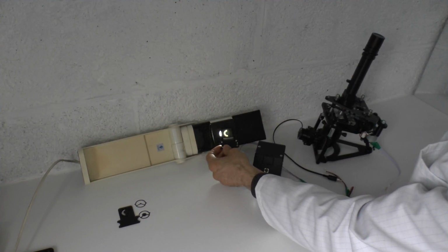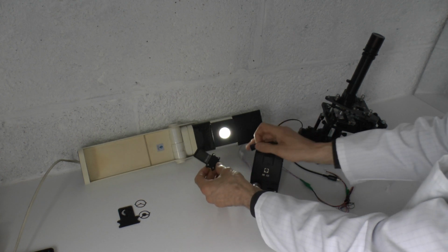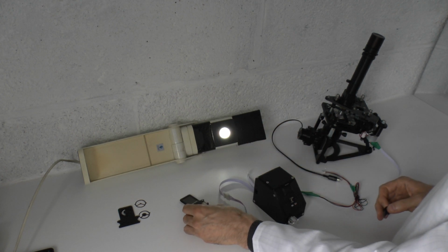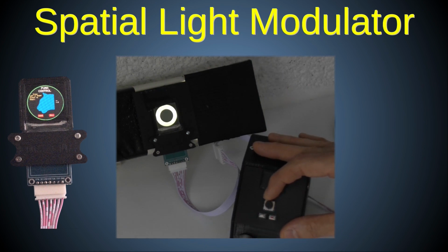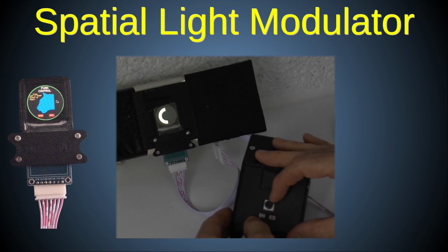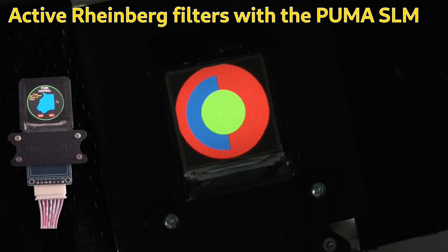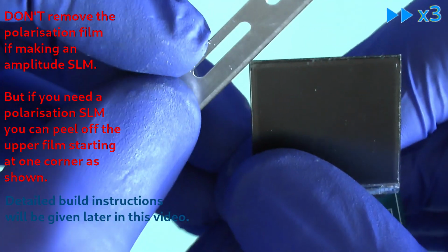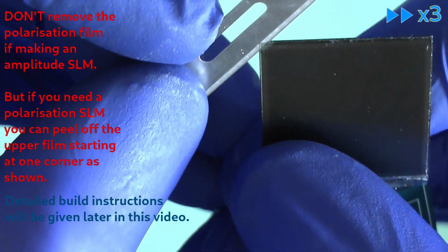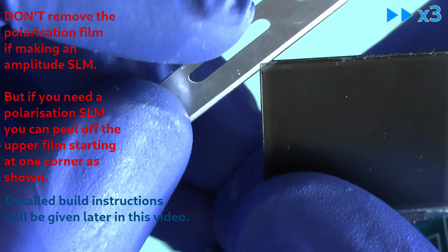The PUMA SLM is most often used as a transmissive amplitude SLM, which uses the polarizing effects of a TFT screen to restrict the passage of light through it at any point across its surface in a way that can be controlled by a computer. However, if you remove the upper polarizer filter from the TFT, then it becomes a polarisation SLM instead.